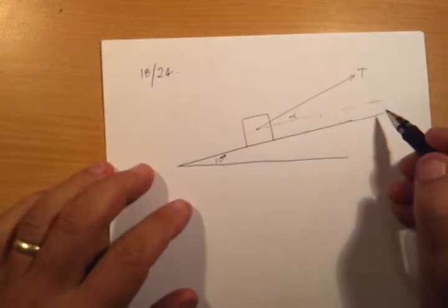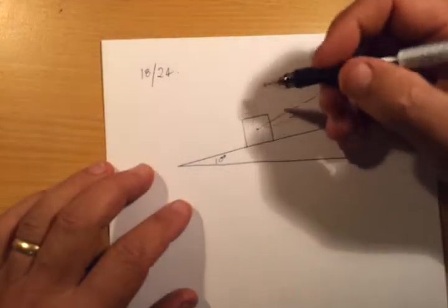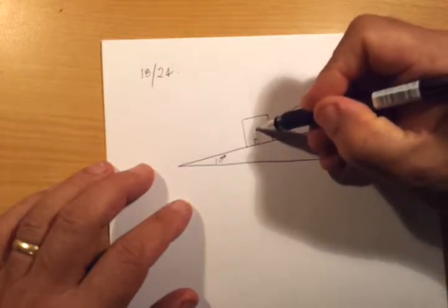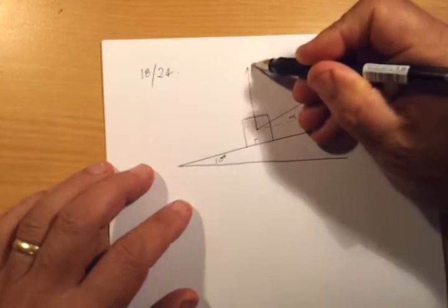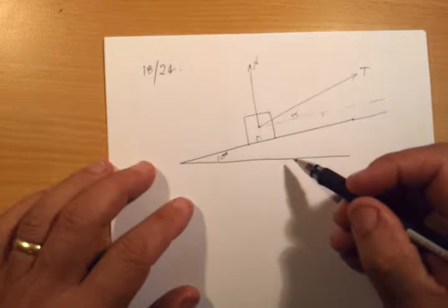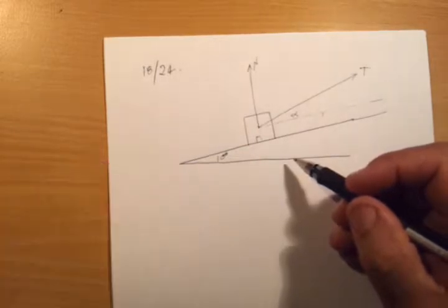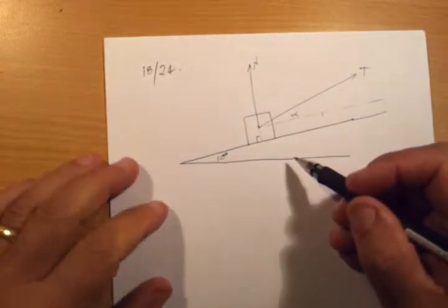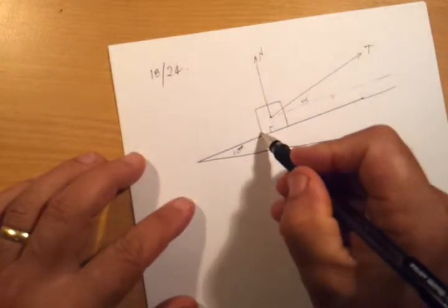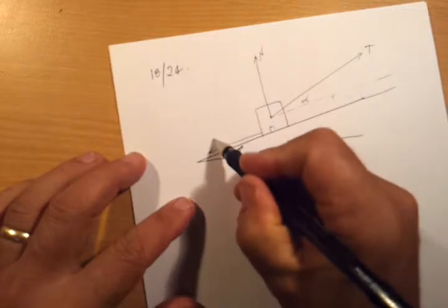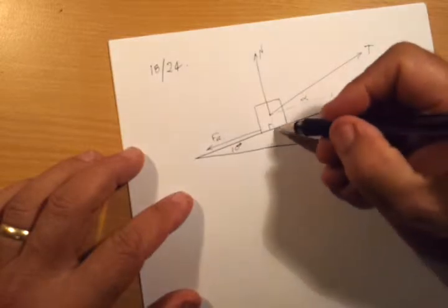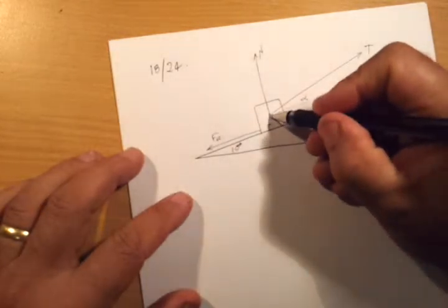And we're going to have a normal force, which will always be the case, pushing up here at right angles. A normal force there. We'll also have a frictional resistance force. Now remember, this is dragging up the plane, so the frictional resistance force will be pulling down the plane because it always opposes motion. And we've got a weight component force which will act directly downwards here.